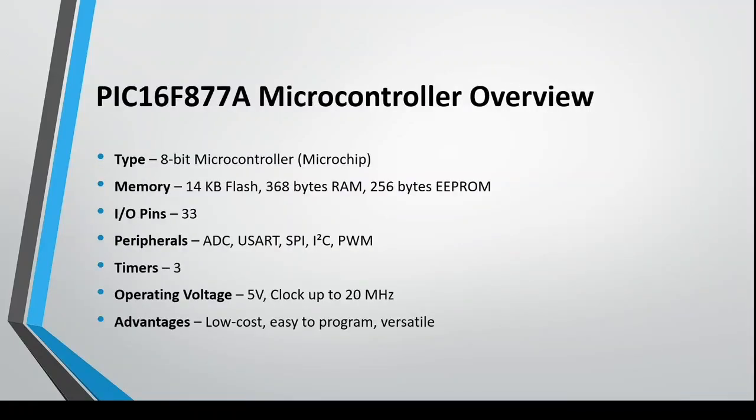Microcontroller overview. Here we are using the PIC16F877A microcontroller. It is an 8-bit microcontroller. It has 14 KB flash memory, 368 bytes RAM, and 256 bytes EEPROM. It contains 33 input-output pins and peripherals such as ADC, which is analog to digital converter,